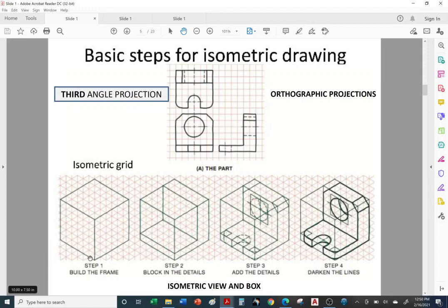If the length was, let's say, 2 inches, then you would draw a line 2 inches. Then we have the depth of the part. Let's say it was 2.5, then you would draw a line at 2.5 inches in length using your scale or ruler. Okay, so you would draw a rectangular box. Just makes it easier when you draw a box, and typically you would draw with very light lines, because you're going to go back and erase any evidence that you cheated by using a box. Okay, then you start drawing the part.